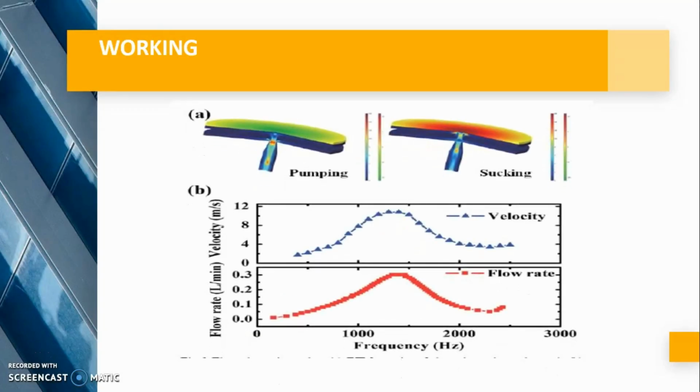As shown in figure 6a, the active micro air cooler can generate a high-speed air jet flow. Such a high-speed air jet flow can drastically reduce the thickness of the laminar flow layer and enhance the local heat exchange coefficient. In addition, the air jet flow generated by the micro air cooler is unidirectional, where cool air is sucked from the rear of the micro air cooler and pumped out from the nozzle. The micro air cooler works like a fan, generating a net air flow. This ensures the air jet flow of heat exchange is always good, and the heated air can quickly leave the heat dissipated to the environment.